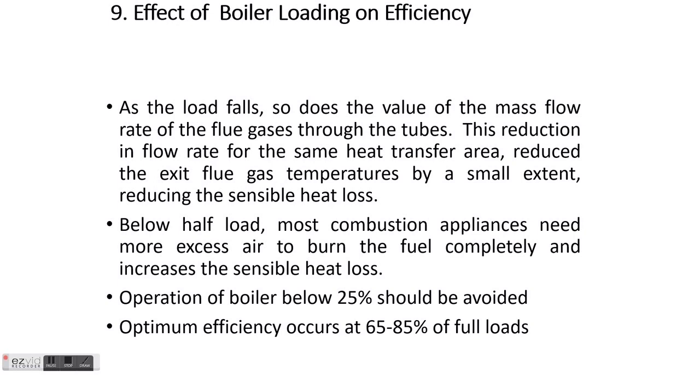The factors affecting boiler efficiency are: as the load falls, so does the value of the mass flow rate of the flue gases through the tubes. This reduction in flow rate for the same heat transfer area reduces the exit flue gas temperatures by a small extent, reducing the sensible heat loss.